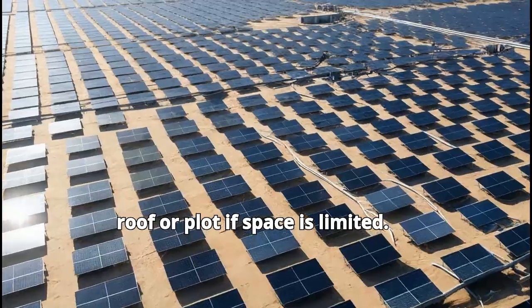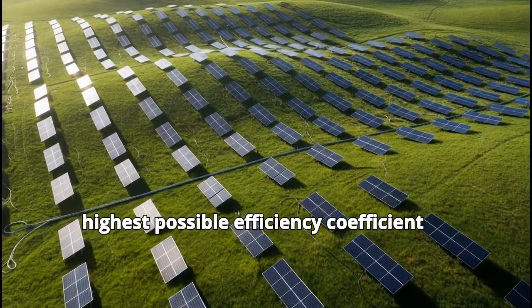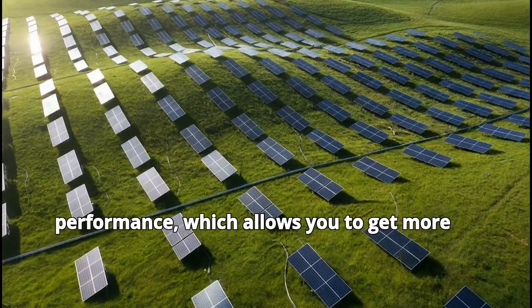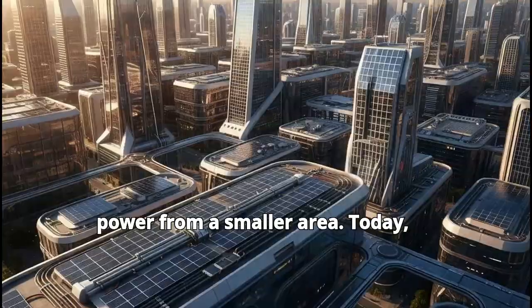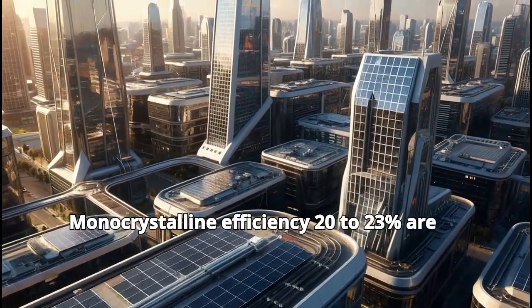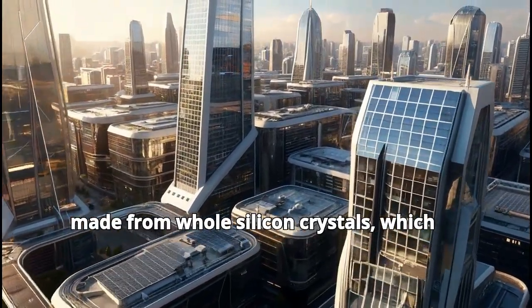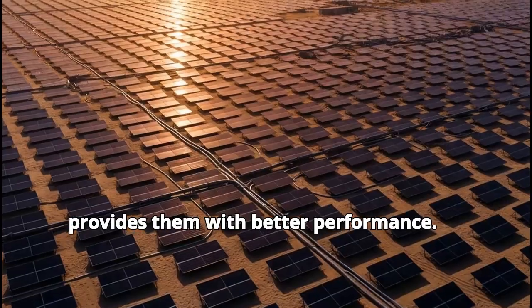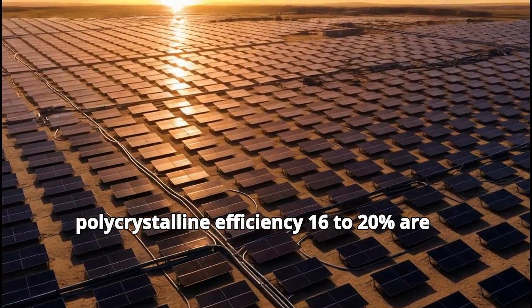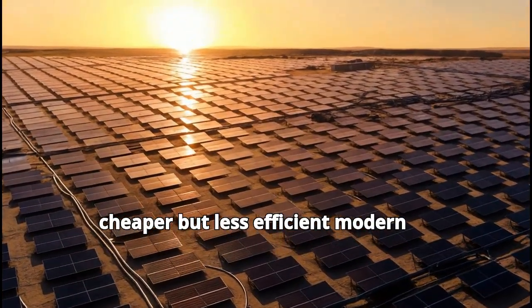If space is limited, priority is given to panels with the highest possible efficiency, coefficient of performance, which allows you to get more power from a smaller area. Today, monocrystalline and polycrystalline panels dominate the market. Monocrystalline, efficiency 20 to 23%, are made from whole silicon crystals, which provides them with better performance in low light and higher efficiency. Polycrystalline, efficiency 16 to 20%, are cheaper but less efficient.